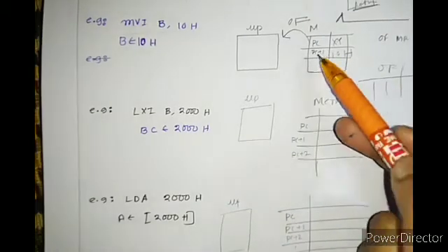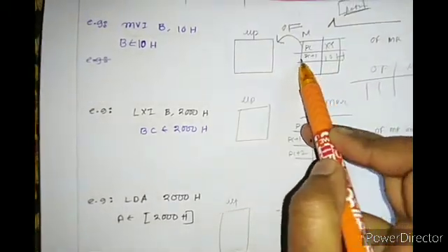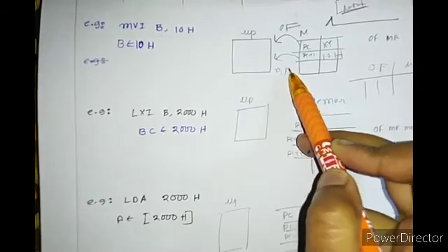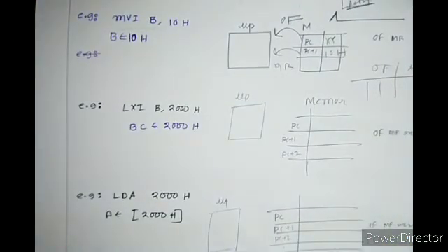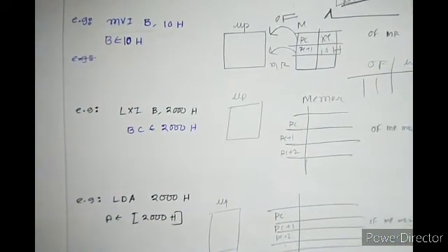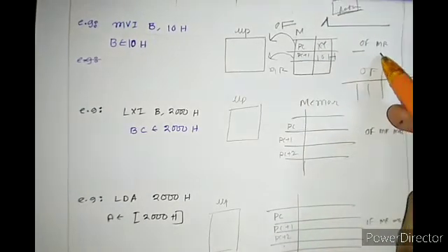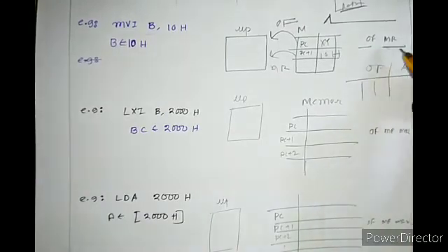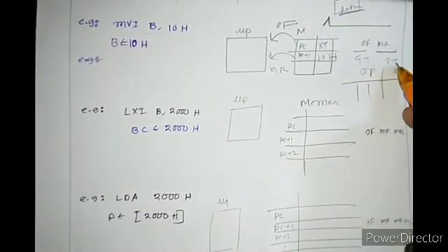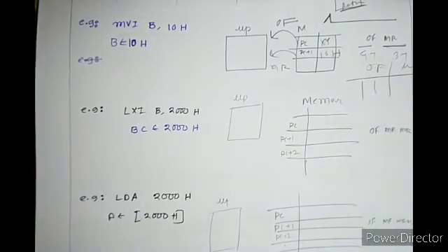Then there will be another machine cycle, which is memory read. So how many machine cycles are required to perform this instruction? First opcode fetch and then memory read. So how many T states? 4T and 3T, that is 7T.